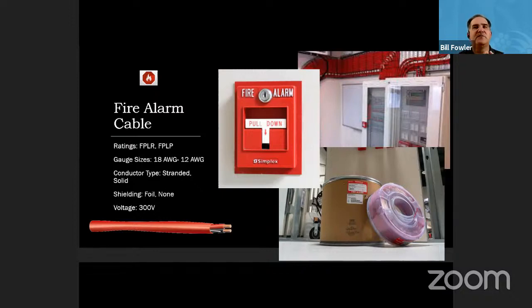So this right here really helps because most of the time you typically would deal with reels in the fire alarm world. So you have to have somebody manning that reel as you're pulling cable, make sure it didn't overspin. So now with this application with the barrel and coil packs, that's a single person operation. That coil pack has a little bit of resistance to it. Nobody has to man that. You can lay it on the floor or you can use our coil pack carts, but you can just lay it right there where it's going in the system and have it pull out. It's not going to overspin because of that back drag.